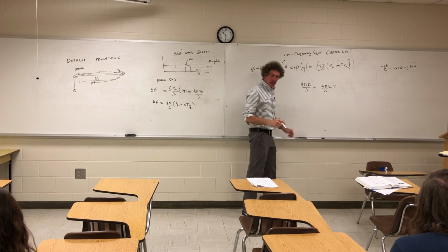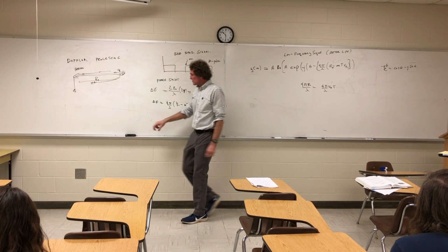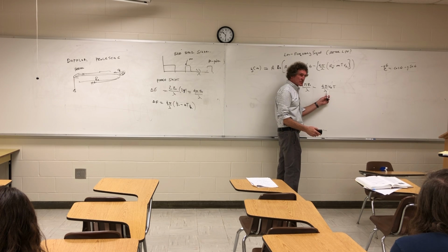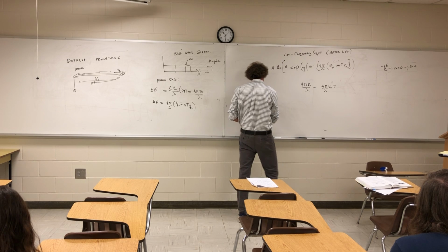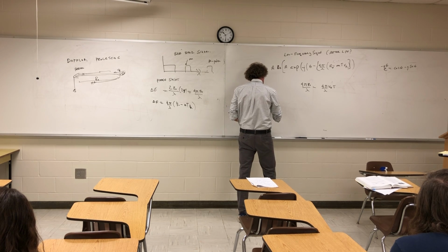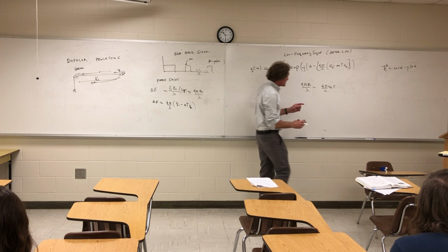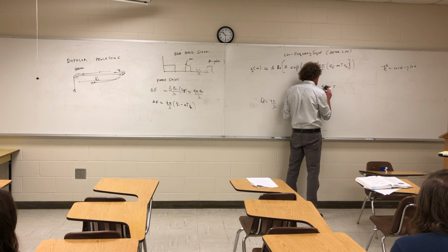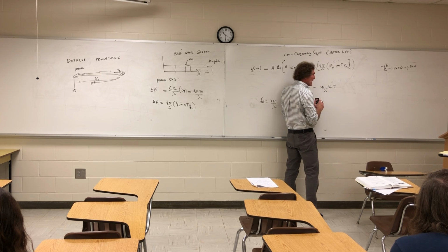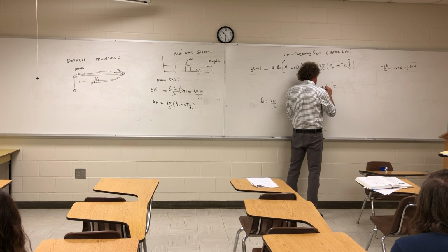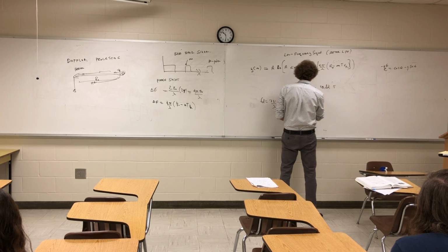And here's what happens right here. What they do is break this out so it looks like a Doppler velocity, or Doppler frequency. What is the Doppler frequency? Isn't F Doppler just 2v over lambda, right? So what they do here is they leave a 2 pi out in front. And now I have 2v over lambda, and that is F Doppler times t.